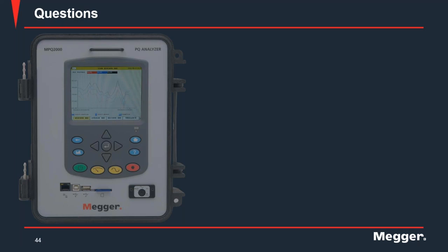But when you're seeing a DC overvoltage, one thing to keep in mind is that the DC bus is going to be generated from AC rectifiers. Depending on the design of the AC rectifier, the voltage you get on that bus is going to be about 35% higher. If you have a 3-phase rectifier, that voltage will be about 35% higher than the RMS voltage coming into the rectifier. So you'll automatically see that. But I see in the question that you've also tapped down, and that really hasn't helped the problem.